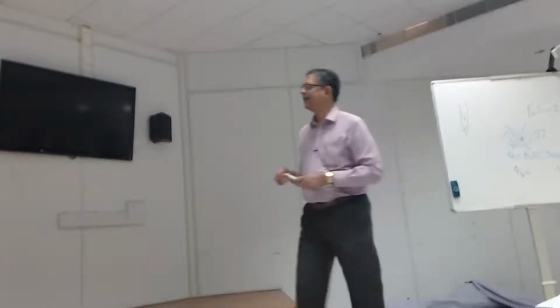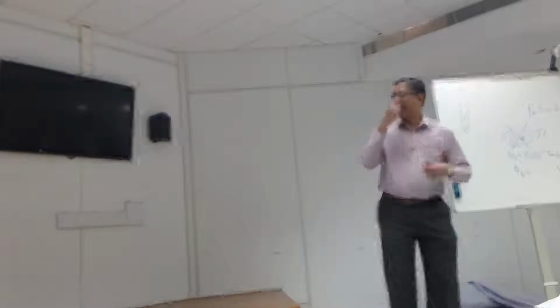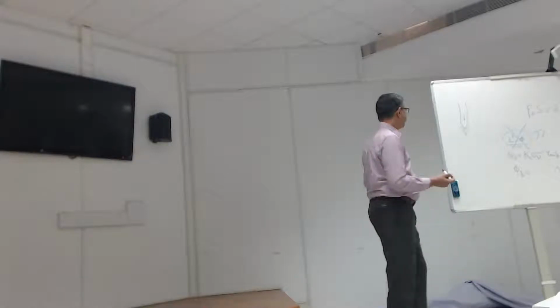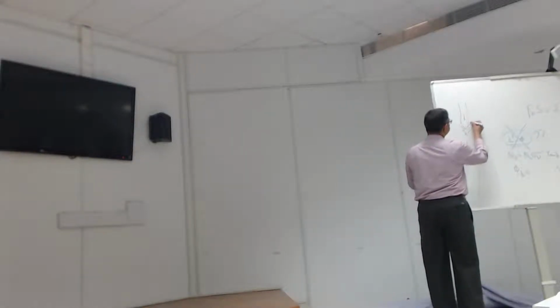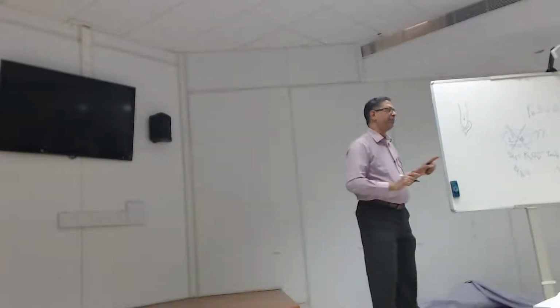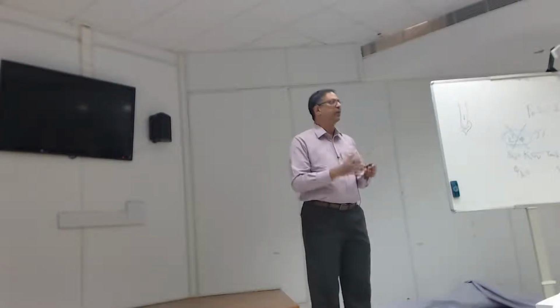So if the soil is undergoing this dilation at the pile tip, then that's going to change its stress state because the volume is changing, and therefore the contribution it can make to the skin friction. So by the time it came from here and arrived here, according to the setup mechanism, I'm in a different stress state compared to when I started here. Now we're going through all this detail because it's important to get the soil mechanics right.